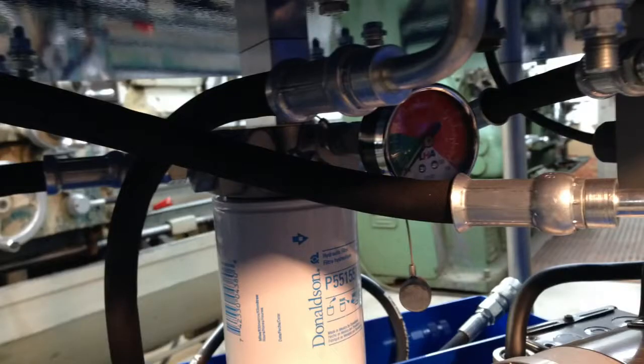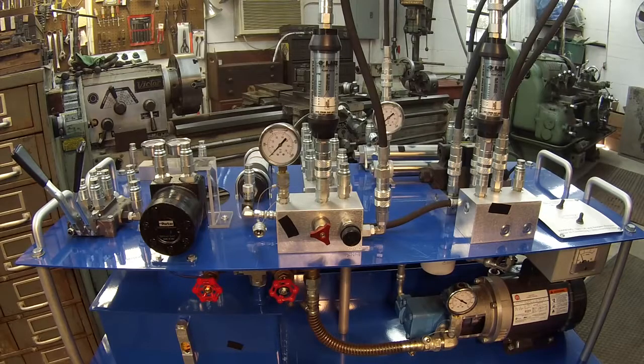You have a spring that's called a bypass spring. As that filter media gets clogged up, that spring pushes open and your fluid starts going straight through your filter and nothing gets filtered. So it's very important to make sure you have a bypass indicator on your filter, which I have on there, but it's very difficult to see because it's way up under there. Okay?